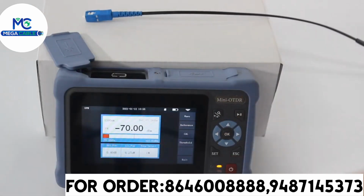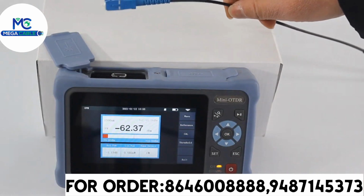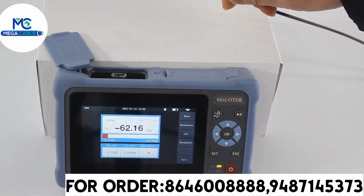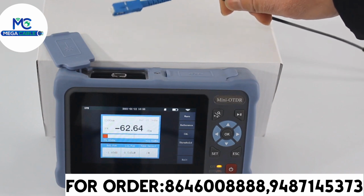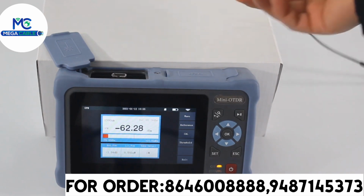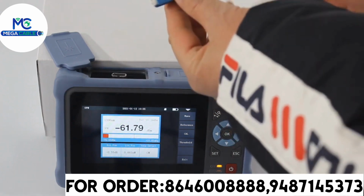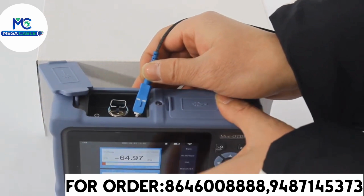Click OPM. This is FTTH drop cable. OLT and set office is transmitting optic signal. The downstream of OLT is 1490 nanometer. Insert FTTH drop cable into OPM port.